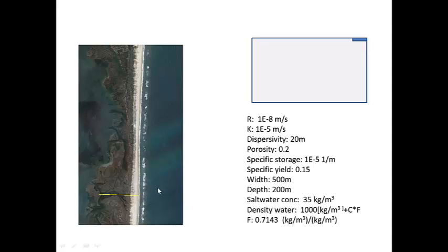We'll assume that we have constant head on this side, the ocean, and also constant head over here in the bay behind it. And we'll, at least at first, assume that the properties are uniform, and as a result of that, we have some recharge here, and that would cause a divide to form right here in the center. So our model will only consider 1/2 of the island, from the divide over here to the ocean.